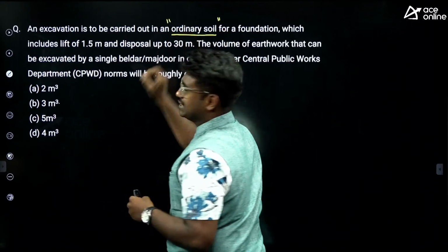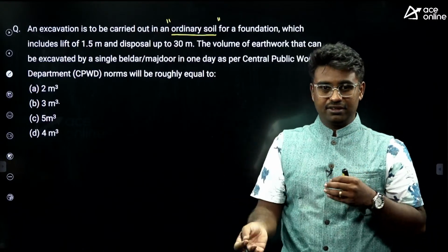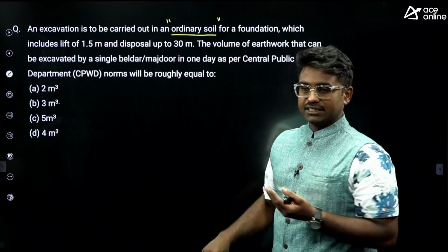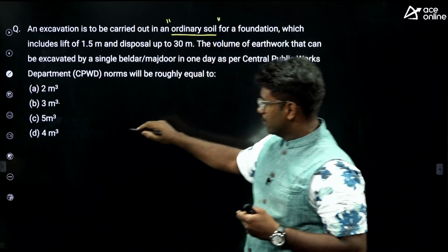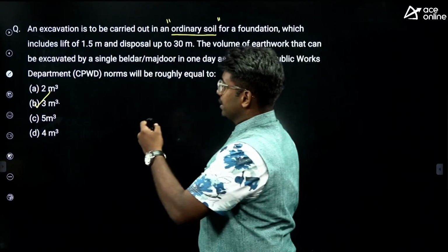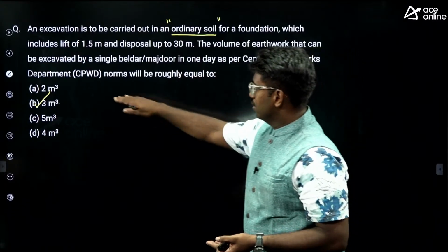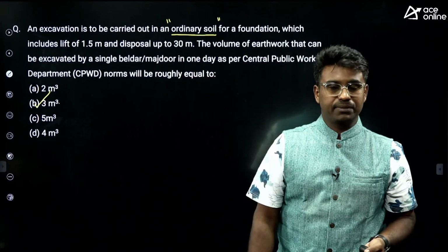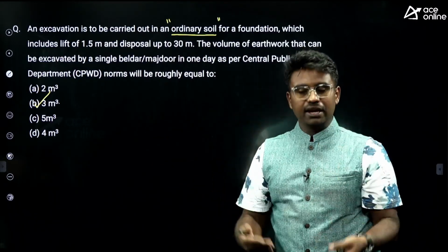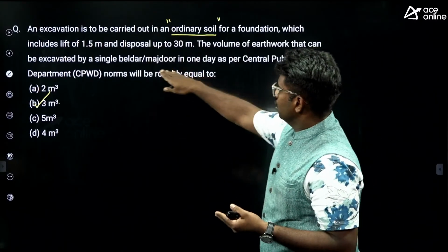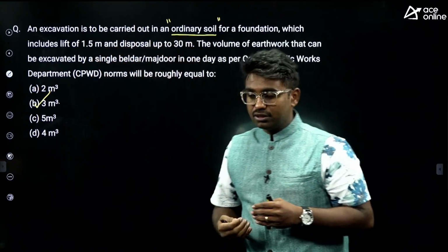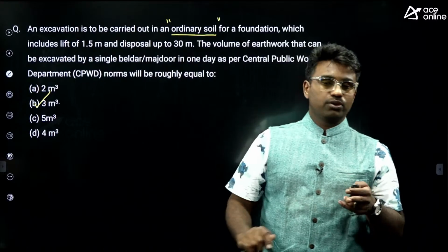This seems like a huge question, but the answer is given directly. If you just go through that video, you can see this. Ordinary soils, blind answer, 3 meter cube per day, as per Public Works Department. The work done by a mazdoor or a beldar for this type of work, ordinary soils excavation, is 3 meter cube.